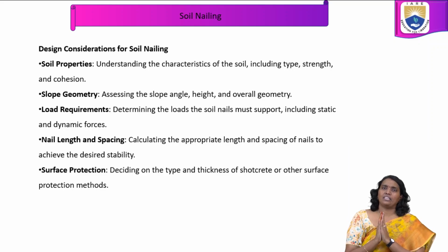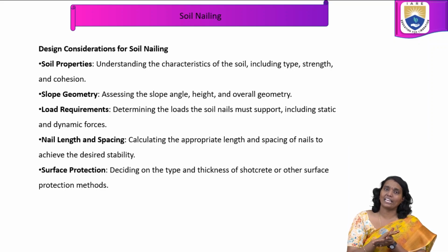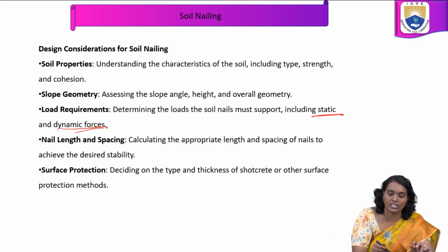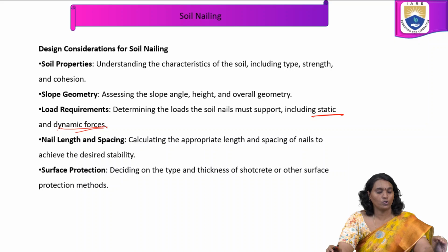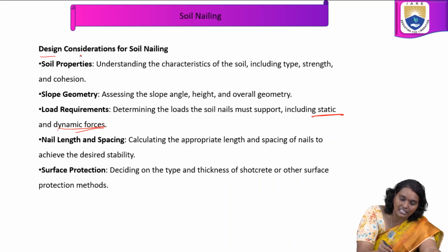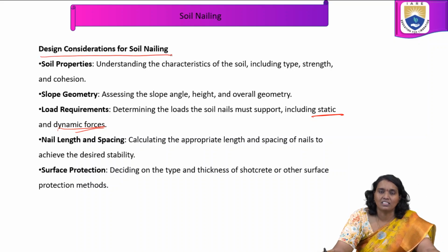In load requirements, we determine the loads the soil nails must support, including static and dynamic forces. So it depends upon whether it is static or dynamic forces, and based on that we choose the load requirements. This also plays a crucial role in the design considerations of soil nailing.